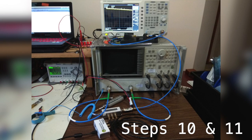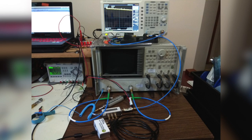While measuring the DUT in steps 9 through 11, power in the VNA measurements can be a serious consideration. If you have a lot of gain in your amplifier, you don't want to overdrive the VNA port or the spectrum analyzer for that matter.